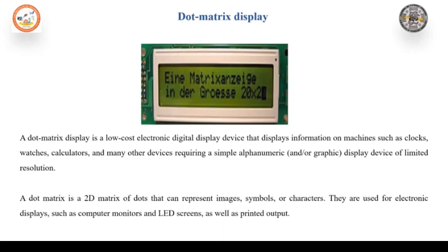In the dynamic display, only one column is energized or driven at a time, and the 5 columns are driven sequentially. When the first 5 columns have been driven, a timing pulse changes the code input to ROM to correspond to that stored in buffer 2.